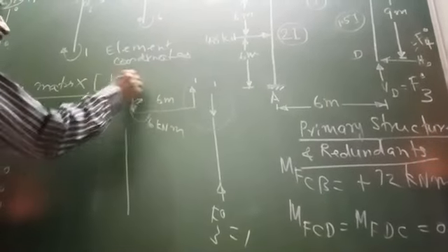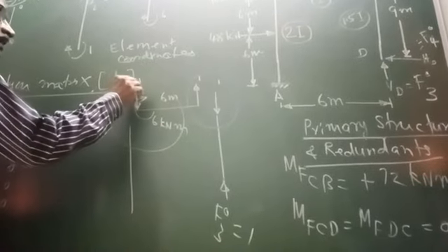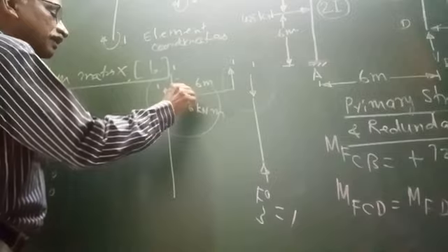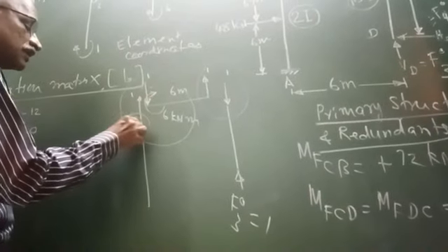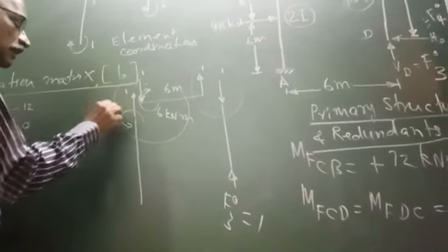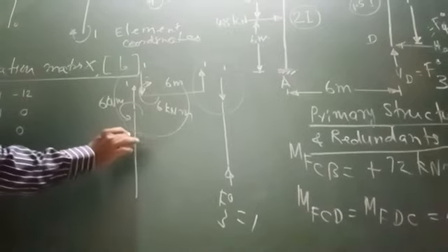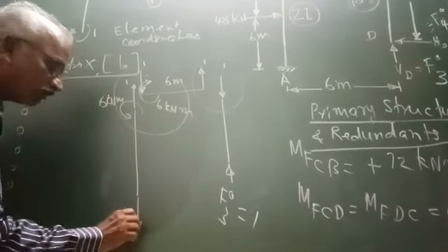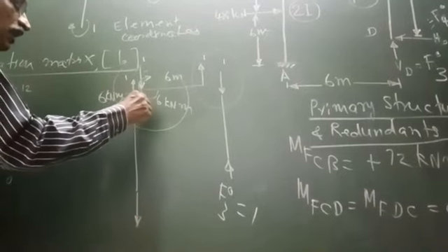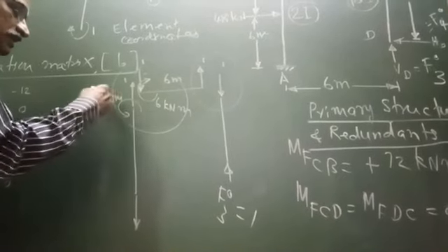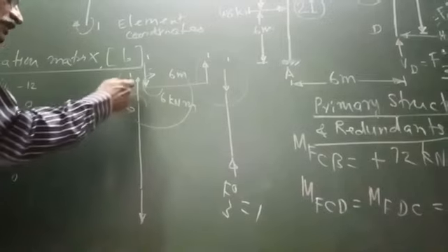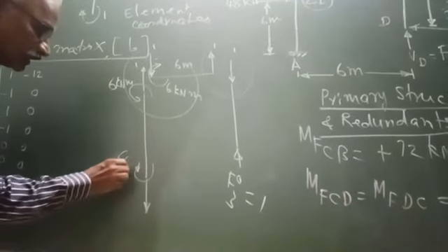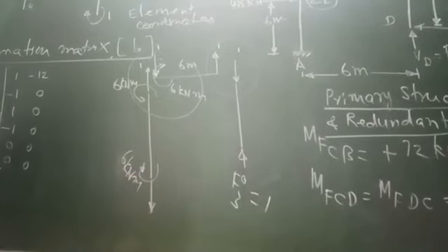Now coming to this joint, when this is 1 downwards, this will be 1 upwards. This is clockwise 6, therefore this is anti-clockwise 6 meter. Now coming to this member equilibrium, when this is 1 upwards, this is 1 downwards. This is anti-clockwise 6. It is not subject to any lateral force, no problem. So this is minus 6, therefore this will be plus 6 kN-meter.